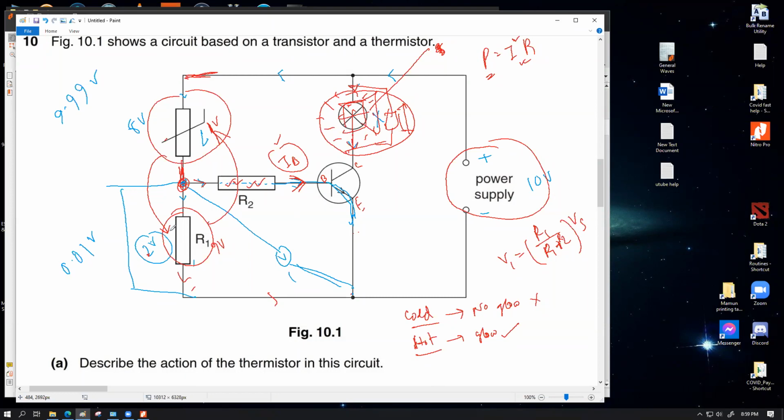So if the temperature goes below that value, that is gonna light up this bulb. Now you might wonder, how on earth are we going to use the same device for two different cases? That choice actually depends upon the choice of this resistor, because you have to understand, it is this resistor that will share voltage with this one from the power supply.